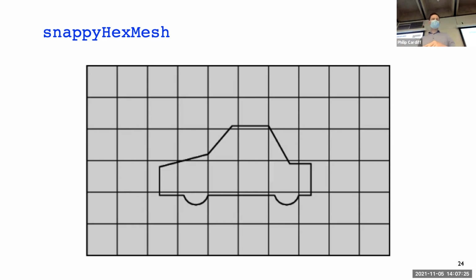So when we did this in ANSYS, SpaceClaim had an option to build that block for us. There was some option where you say make and close the domain that we used in the tutorial.